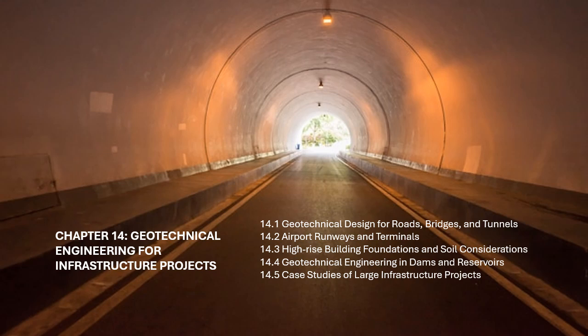Groundwater and seepage control. Groundwater conditions play a crucial role in dam foundation design. High groundwater levels or seepage through the foundation can undermine the stability of the dam. Engineers must assess the hydrogeology of the site to determine the potential for seepage and design appropriate drainage and cutoff systems, such as cutoff walls or impervious layers, to minimize the flow of water through the dam's foundation.